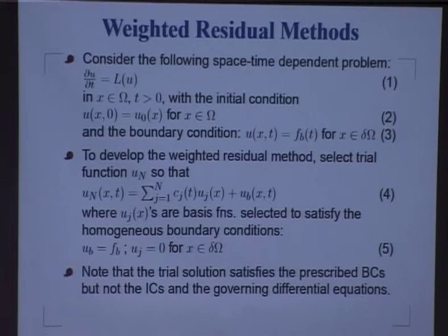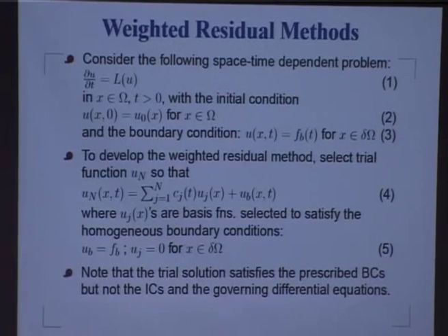If it was pure separation of variables, I would not identify this C of t with individual nodes. There is an implicit space dependence also built in there. In fact, I fail to see in most books on finite elements where this part is highlighted, but that is one of the strongest points of FEM, which people have not really highlighted.